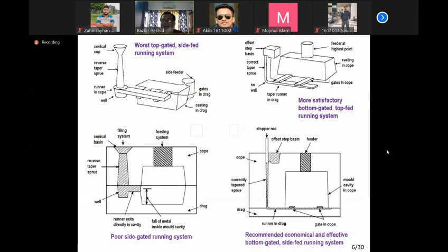Okay, this is a version of the bottom pouring systems where the channels are even narrower. So instead of this one, here is a very narrow sprue. It could be rectangular, it could be circular as well. And the runner is very slim, very thin, and gates are also a small section. As a result, the liquid metal requirement in the gating system is very less.